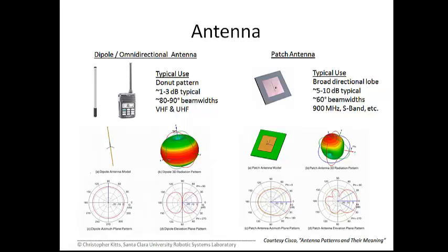So really what's happening is the majority of the energy is coming out radially from the mast of the antenna. If I want to do a good job of transmitting in a certain direction, I don't want to point the antenna in that direction, down axially, because that's actually the direction of most loss.